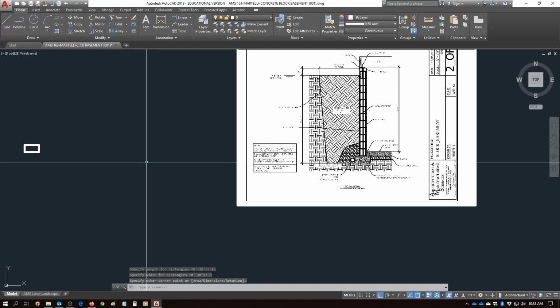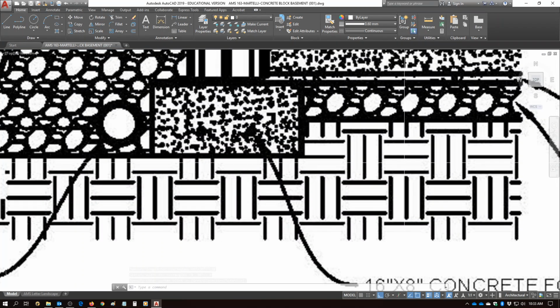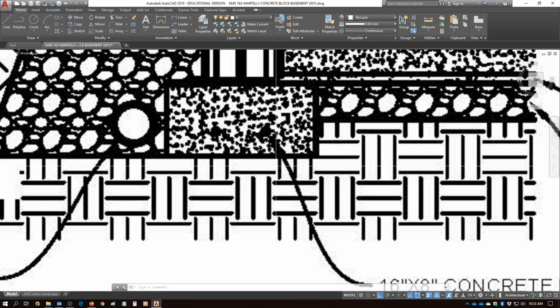Now that rebar, if you look close at the rebar, there's not just one piece of rebar. There happens to be 2 pieces. So let's kind of look at it. I would say that the first piece is about 1/3 away from the left edge. Second piece is about 2/3 away from the left edge, or 1/3 away from the right edge, if you follow me. Not only that, that rebar, well, it's closer to the bottom of the footer.